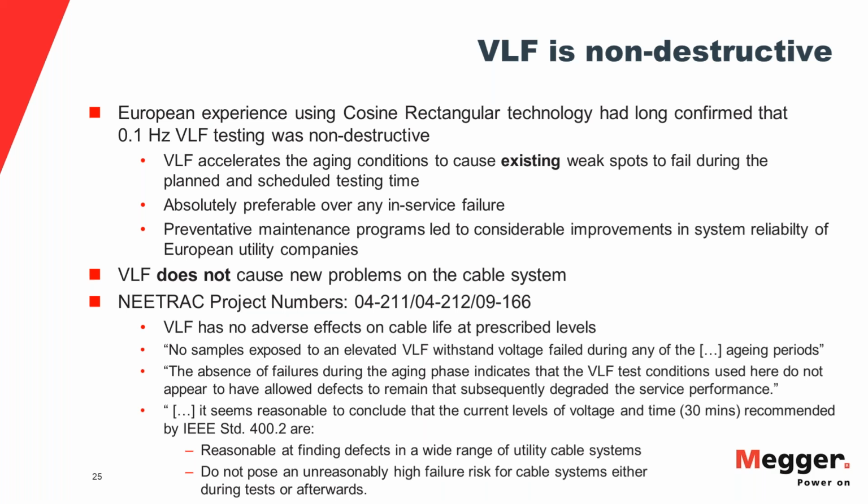But here's the trick. If you have defects in the cable, the test will fail them. It will not introduce new defects. So VLF is not damaging the cable, but it will grow any weak spots and then fail these critical weak spots during the test. So if you don't have any existing weak spots in the cable, the VLF test will pass. And you will see in the second study I brought with me, and we will elaborate a little bit on those values, that you can see that VLF is a non-destructive test.